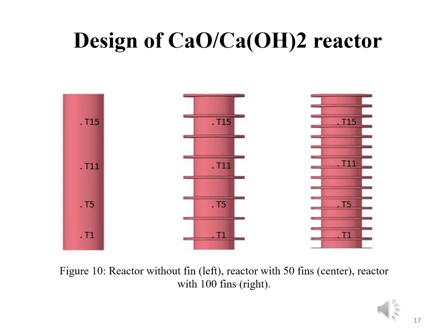Second with 50 fins was done by Harsh Nakum, and third with 100 fins was made and done by Shivam Parmar. The reaction which was made into focus was the charging, or say hydration process, in which calcium oxide is there on the reactor bed and high temperature steam strikes on it from the top, which results in the formation of calcium hydroxide, and heat is dissipated in the atmosphere.